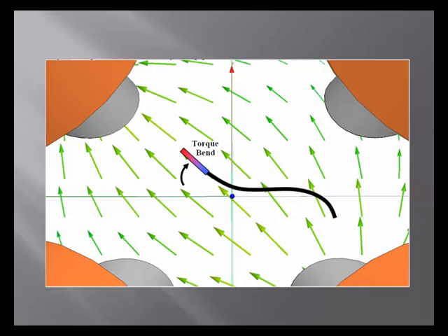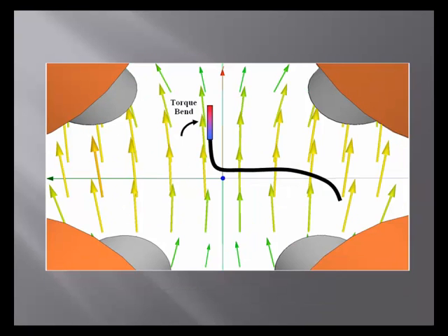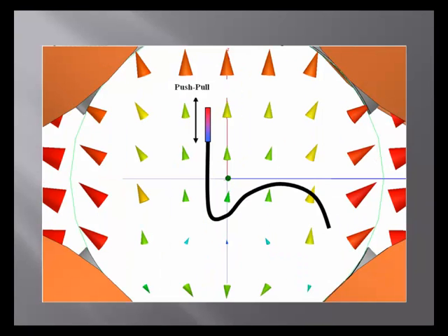It's instantaneous, a 200 millisecond delay, and you can realign the catheter tip in 3-dimensional space, and that's what we call our torque fields. And you can do push-pull by having field gradients so that you can actually go towards the differences in magnetic field illustrated here, so that the catheter can actually move in the direction of the stronger field.